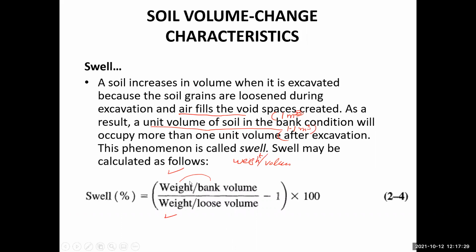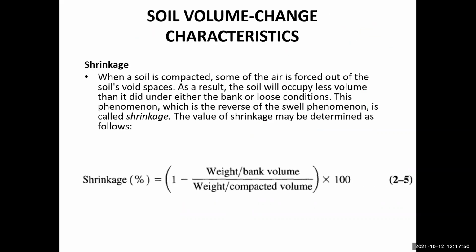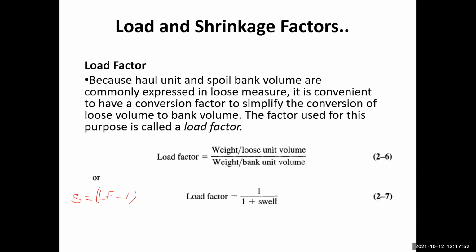So the swell percentage is the weight per bank volume minus the weight per loose volume, multiplied by 100. Okay, since this was in terms of percentage, we can divide by 100 on the other side, and then we can get this formula in terms of the swell and the shrinkage.